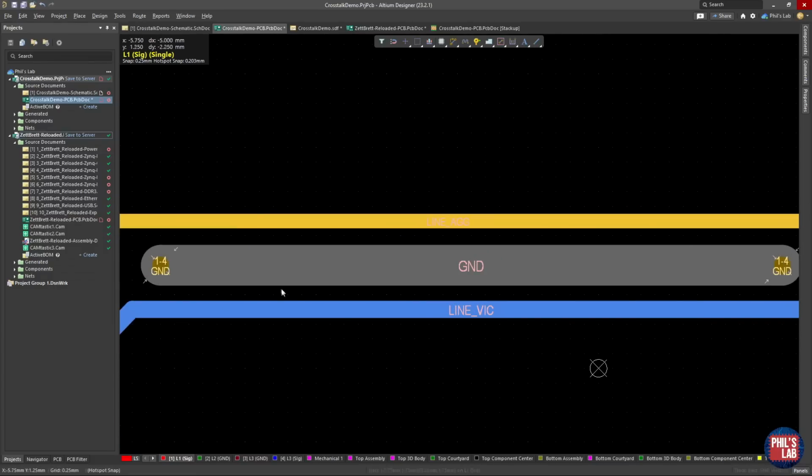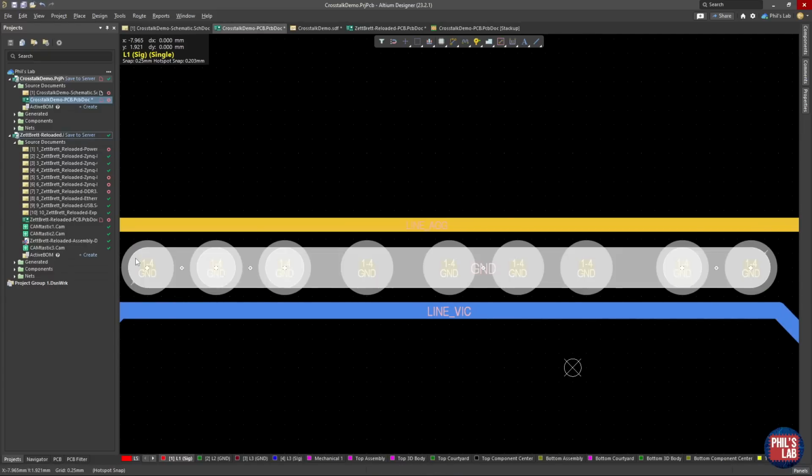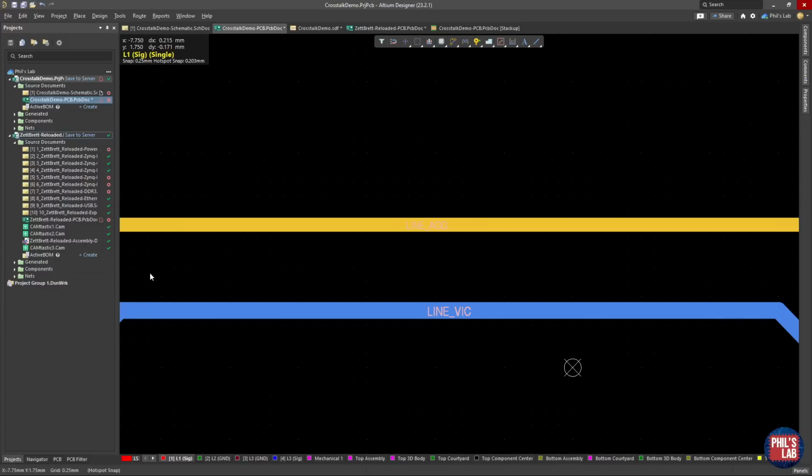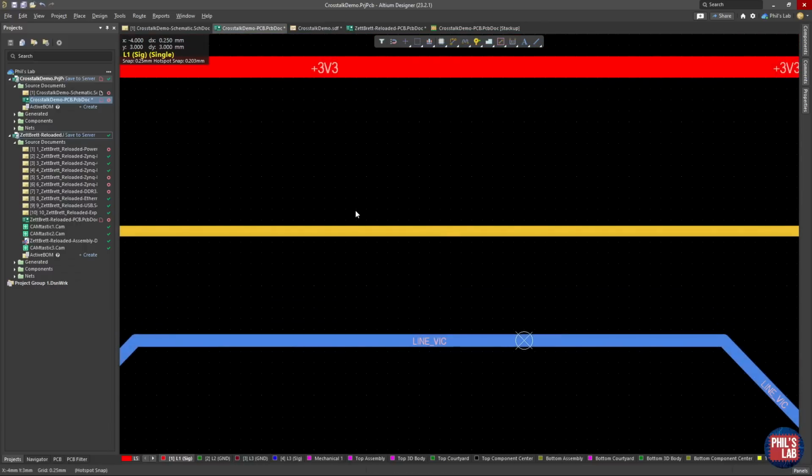This might act as an antenna or even as a bandpass filter between the aggressor and the victim line, and maybe even increase crosstalk. If you really want to do this or must do this, this needs to be carefully planned. You need to place many or enough stitching vias on this grounded trace in the center to make sure it doesn't resonate and doesn't act as a bandpass filter. The spacing of these vias depends on the maximum frequency in the system, in turn which depends on the edge rates in the system. In general, it's probably better if you don't want to calculate and don't want to worry about it, just to get rid of that. There isn't much to be gained anyway, even if you get it to work right. The main takeaway should be maximize your spacing between aggressors and victims.